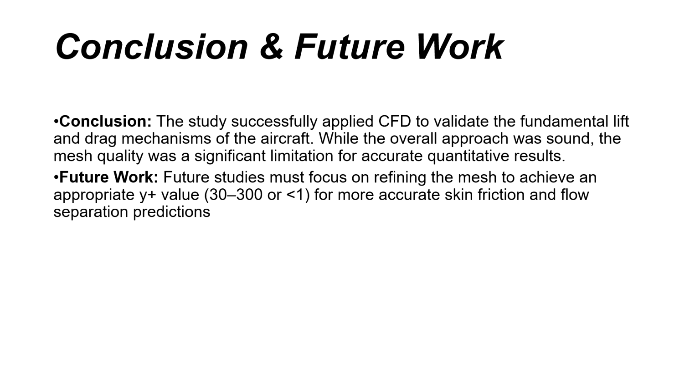To conclude, the CFD study successfully validated the basic lift and drag mechanisms of the Sukhoi aircraft. The simulation captured airflow acceleration, pressure differences, and wake formation, all of which are essential aerodynamic features. For future work, I plan to refine the mesh to achieve y+ values in the appropriate range. This would allow more accurate predictions of skin friction drag, flow separation, and overall aerodynamic coefficients.